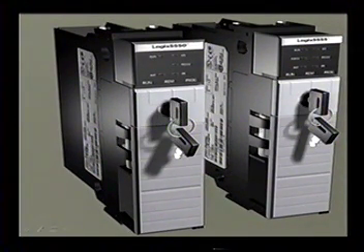Now, you can actually create a fault. If you're downloading this processor and you're in remote mode and you switch it over to run mode, right during the download, you'll fault the processor, and you have to clear the fault and stuff like that. So we'll try and fault a simulator. I don't know if I can or not, but I'll try it. And if I can, then we'll actually clear the fault. If I can't, I'll just show you how to clear it.